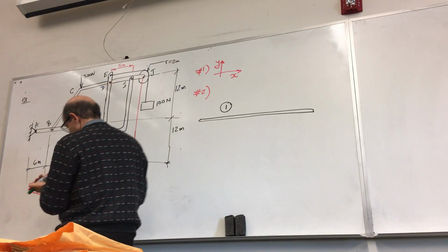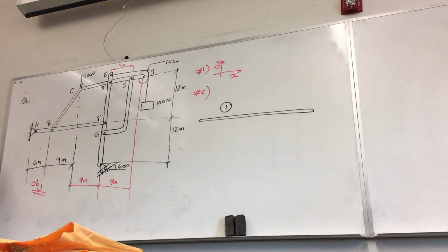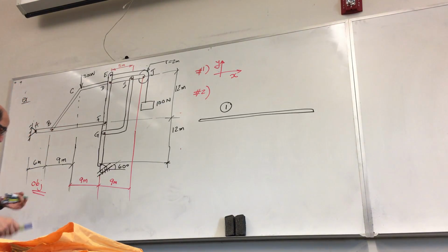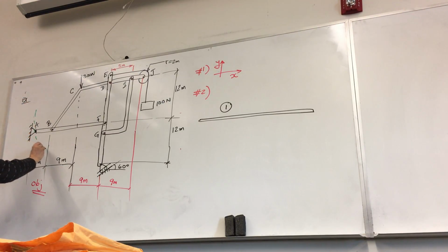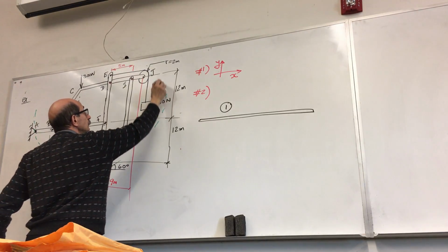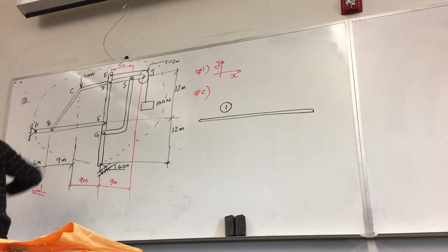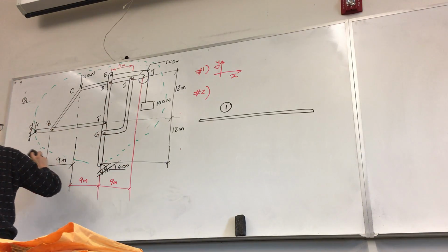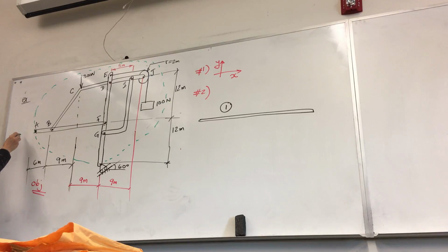So, before doing that, actually, you don't have to start with that free body diagram. It may be actually a good habit that you start with the entire structure as the first free body diagram, especially since you know how to do it, right? It's quite a familiar thing to you. So this is the structure, right? So why not start with that as the first free body diagram, right? So all you need to do is just take these supports away, right? And put back their effect.